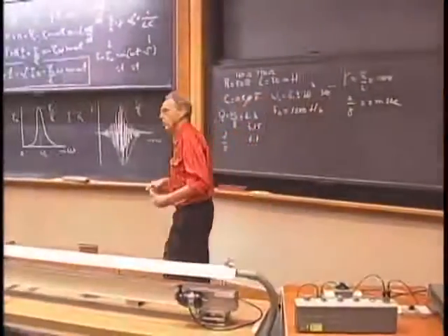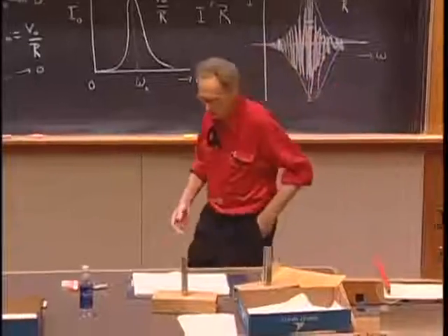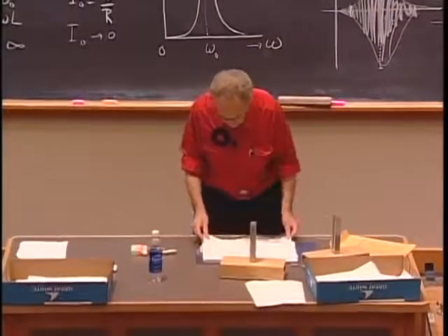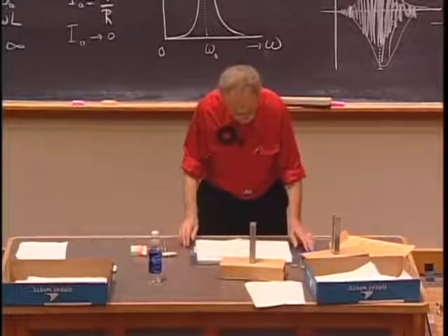So now I will make it 100 ohm. You see it's down by a factor of 2 from here to here. And you may have noticed that it also gets broader, and now I will go to 150 ohms, and you see it's down by a factor of 3. And again, it is broader. So this is an amazing way how with RLC circuits you can do wonderful things, because you can manipulate omega 0 very easily by changing L and C, and you can manipulate the driving frequency also very easily.